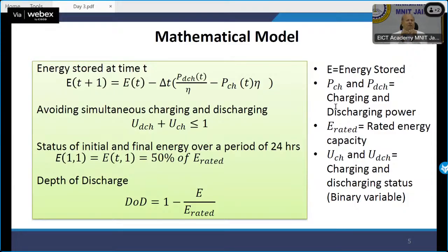So I must allow the battery to either charge or discharge even from the next hour itself. To do so, with a boundary of, let's say, 20% as the lowest energy state and 80% as the upper energy state, I start with 50%, so that the next hour could be charging or discharging, whatever I like to do. Similarly, the ending point will also be 50%.